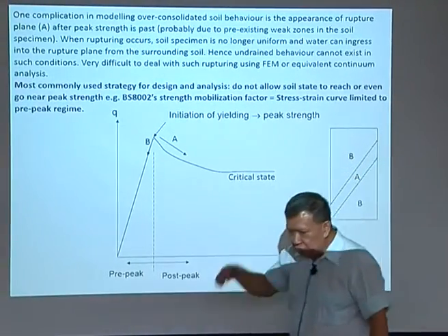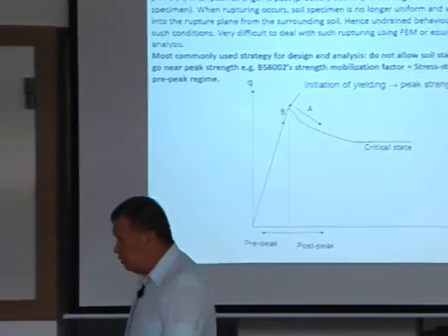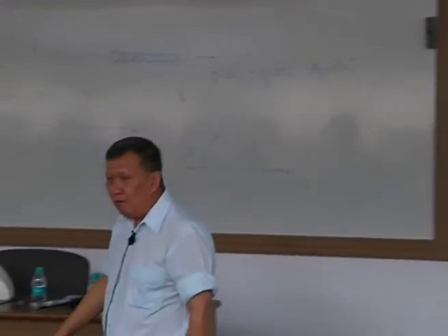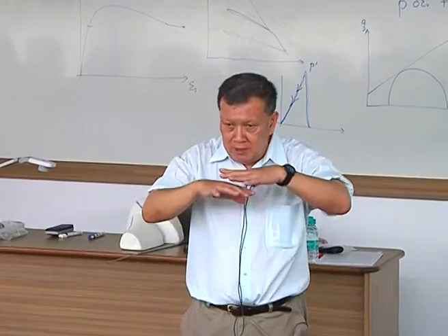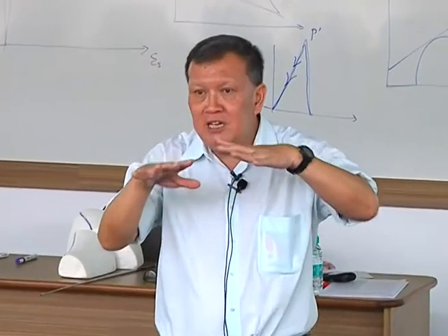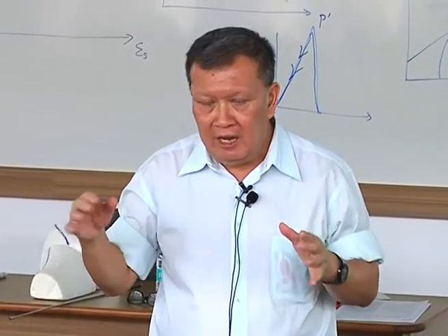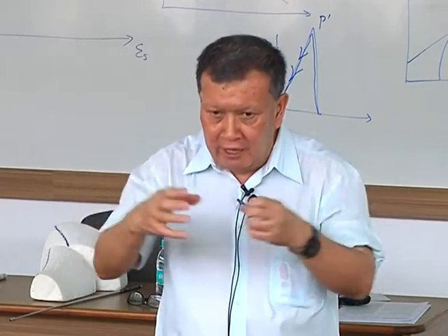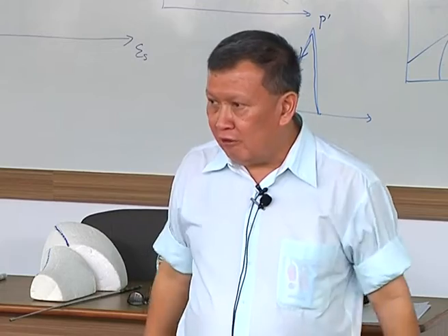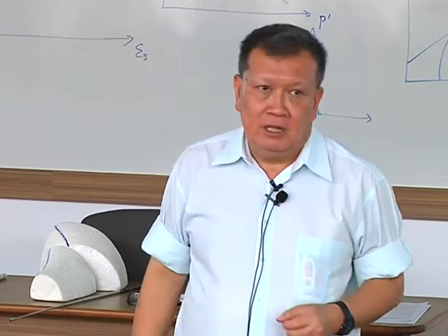Alright? And then you need to put in a frictionless platen. Okay? We use Peter Rowe's method to enforce a frictionless platen by using two pieces of soft rubber with grease in between. There's hardly any friction there. And he sliced up the soft rubber in a star-shaped fashion so that you allow it to expand and contract very easily. So that is the thing.